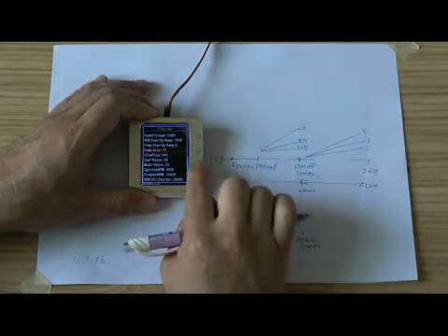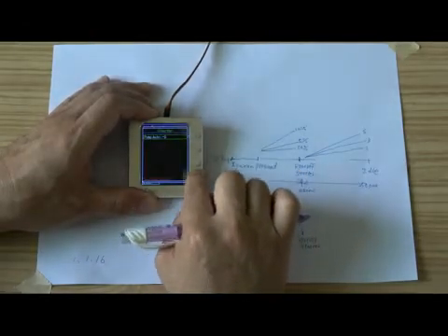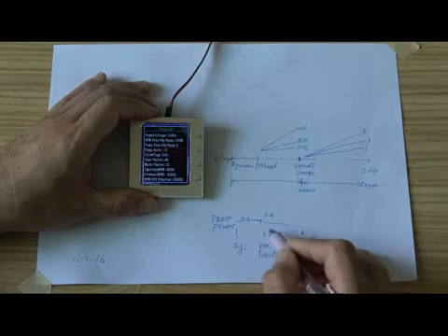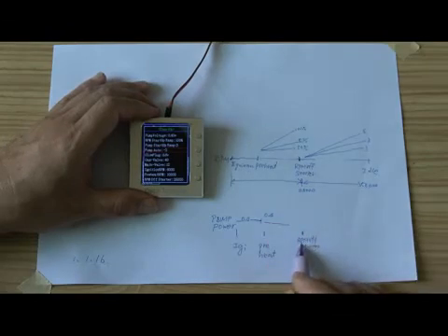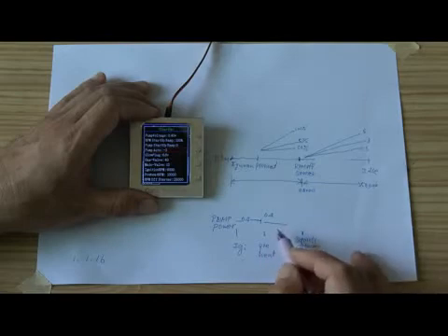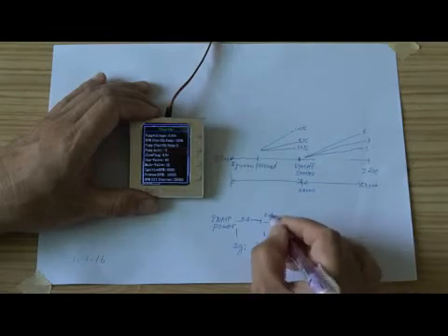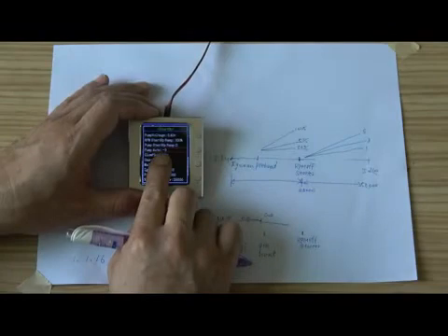And if you find that when preheating to the RPM of the starter the temp increases very fast and too high, you can reduce the parameter.